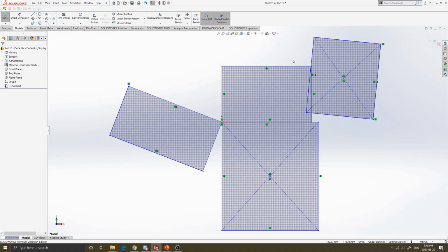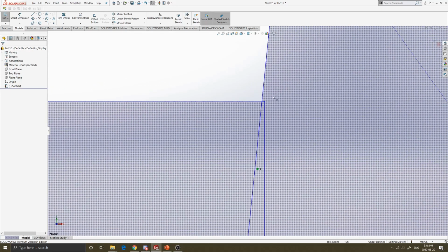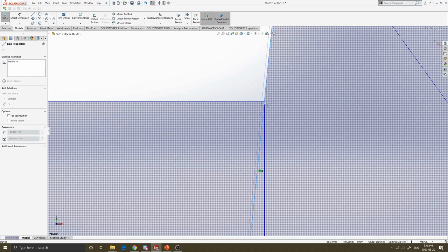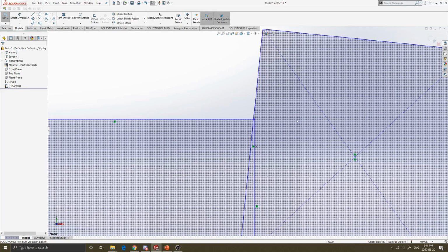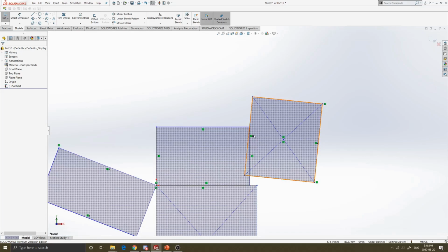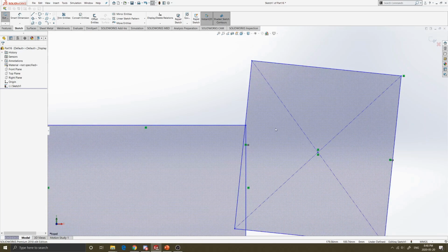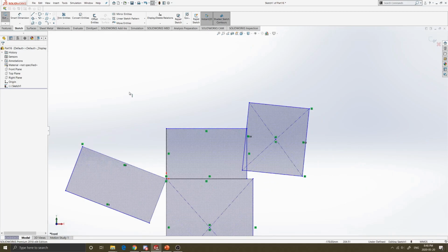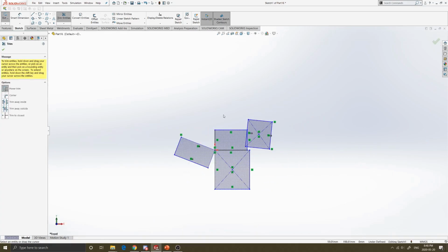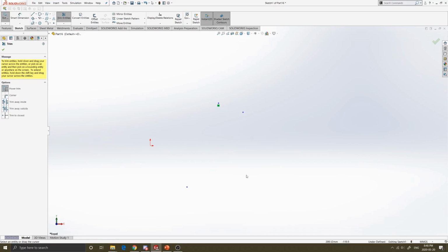Oh, one thing to notice, sometimes when you're drawing lines really quickly, sometimes you think you select the line, a point for it to merge, but sometimes it actually doesn't select it. So sometimes when you want to extrude a profile, like a profile needs to be fully enclosed. Otherwise, it won't be able to recognize that it has a hole in it.